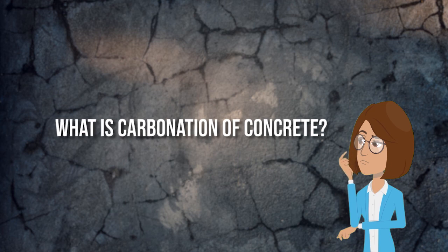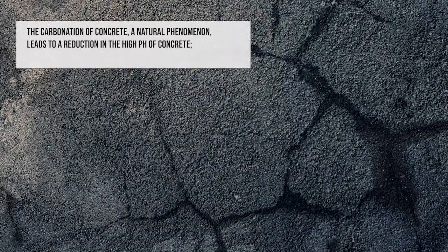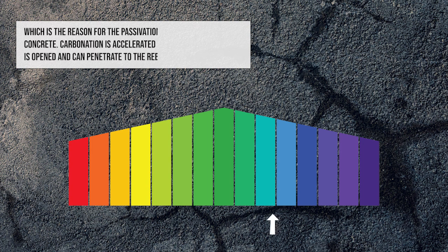What is carbonation of concrete? The carbonation of concrete, a natural phenomenon, leads to a reduction in the high pH of concrete, which is the reason for the passivation of steel in concrete. Carbonation is accelerated when a crack is opened and can penetrate to the rebars much faster.